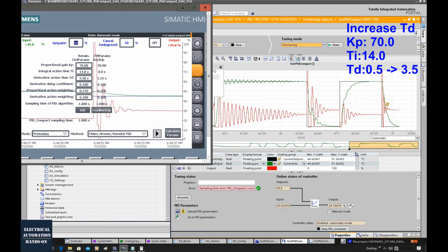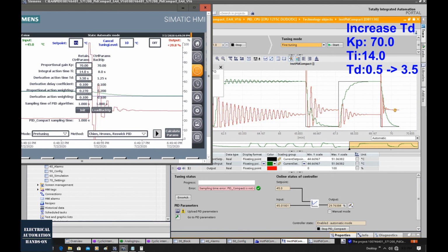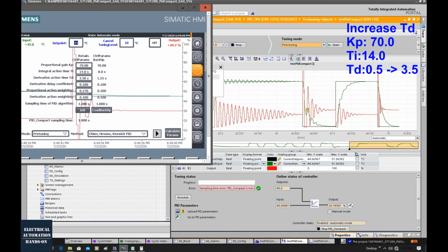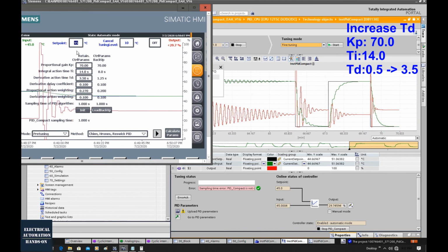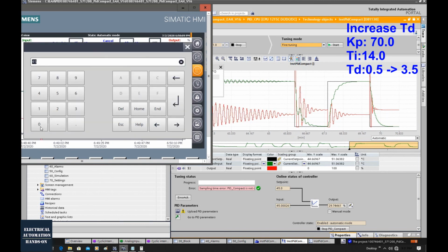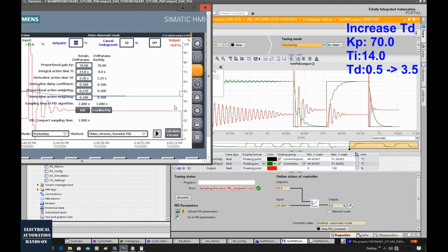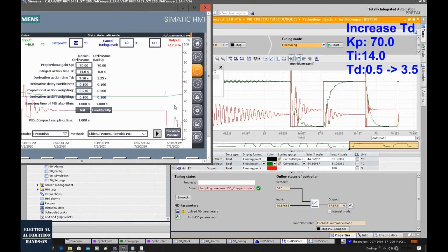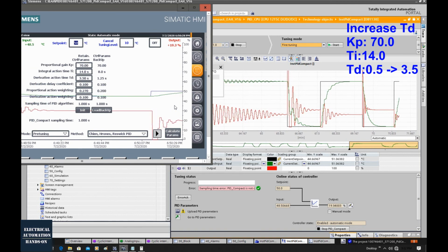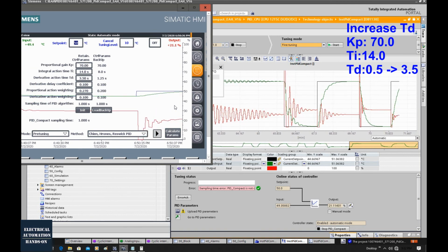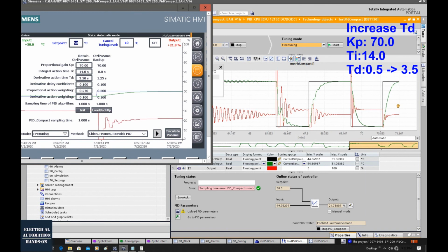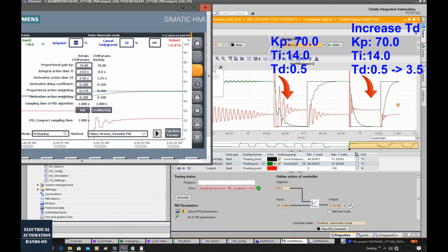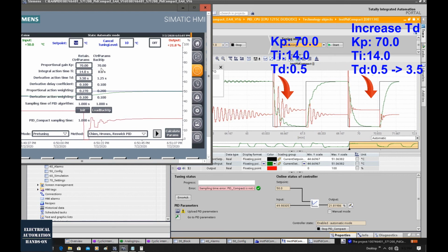As we can see, with this enhanced prediction on the derivative, the process value will not show that hesitant behavior. See, like this. And then let's change this 45 to 50 set point. As we can see, after we increase the derivative, the previous hesitant behavior is gone. So now the process shows very perfect.